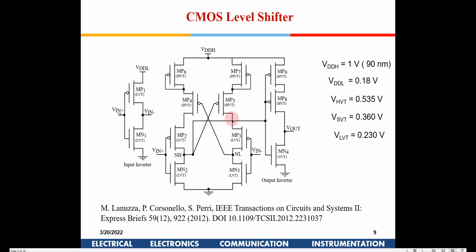So this 0.45 volt becomes the VDD available for these two small inverters, which we are going to operate at 0.8 volt, right? Now the voltage here is only around 0.45. This voltage is also 0.45 and this is around 0.2. So the voltage across here is not 1 but just 0.45. That will ensure that these inverters work properly.